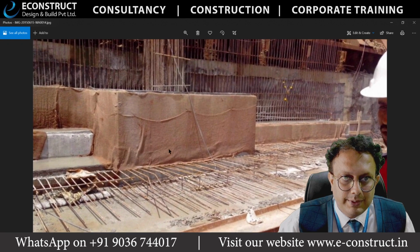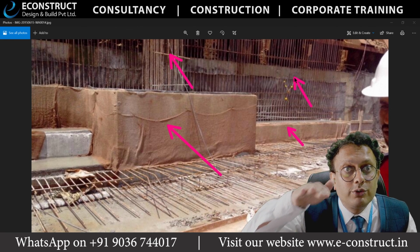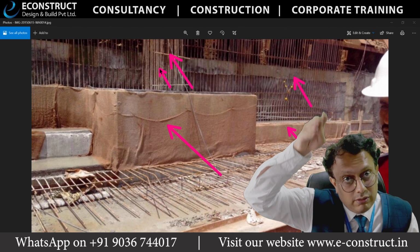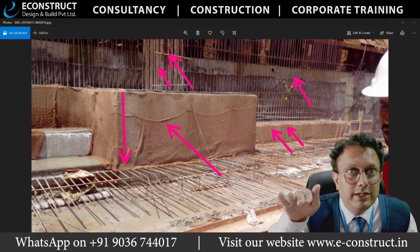This is curing, it has been done. The bottom side, you know that this is basically the reinforcement rebars for the foundations. This is basically the strip footing over here. Pedestal footing for this column, because this is the main column of the tower. The retaining wall will go only up to the ground level. Why would you want a retaining wall above the ground? You don't need it. But the column will go even above the ground. That's why you require such a big depth. But you don't need such a big depth for the retaining wall, because it will be only from the basement to the ground.